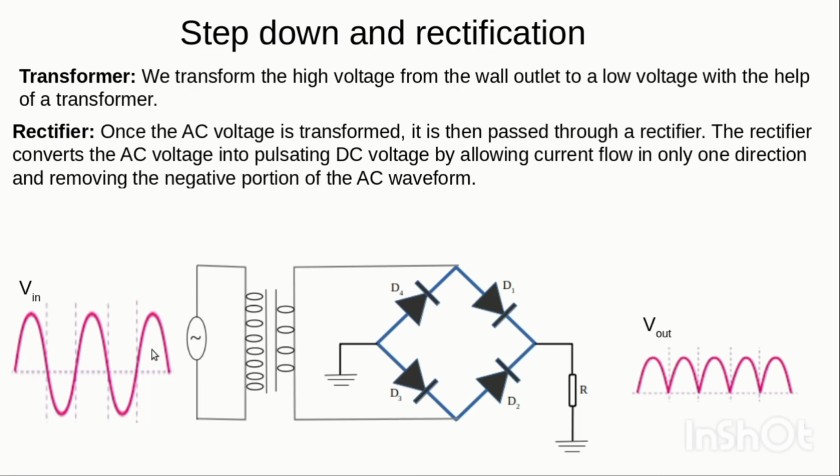What we do is, this first part, which is the positive part of the voltage, goes through this rectifier, right? And when it goes through, here becomes positive, here becomes negative, and in so doing, current will flow through this direction. So we start with the current that flows through this direction. When it gets to this point, it sees this and it sees this. It knows that there is a blockage here, so it goes through this one.